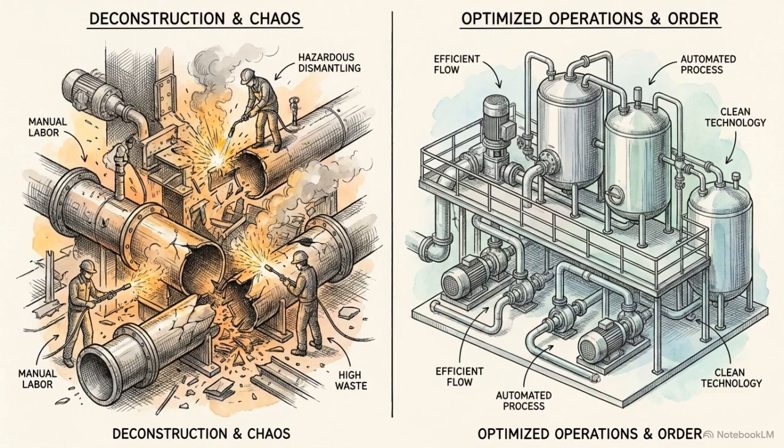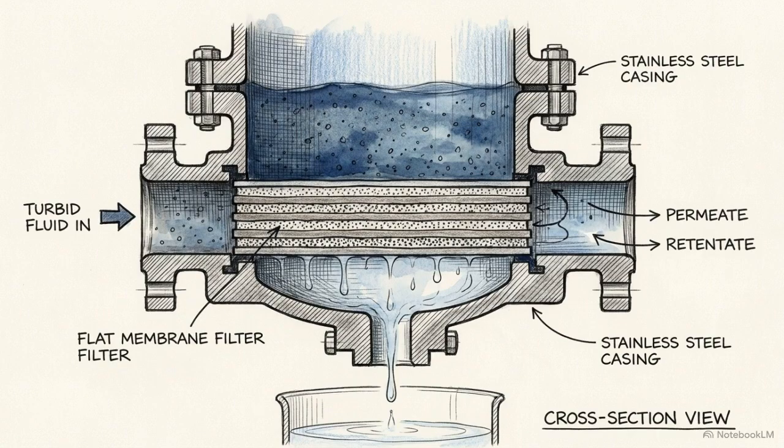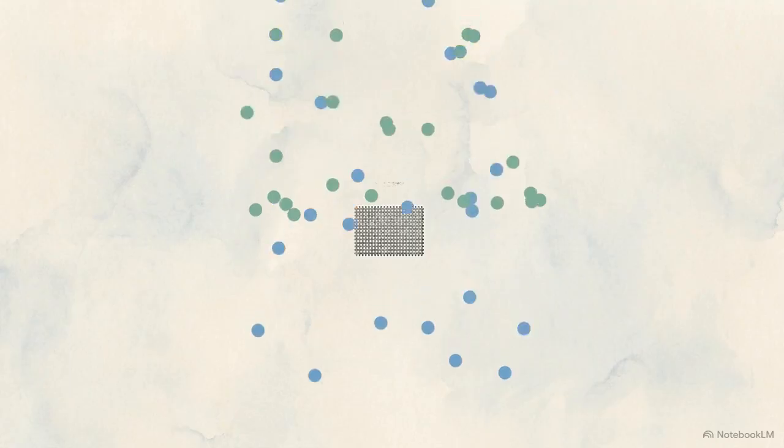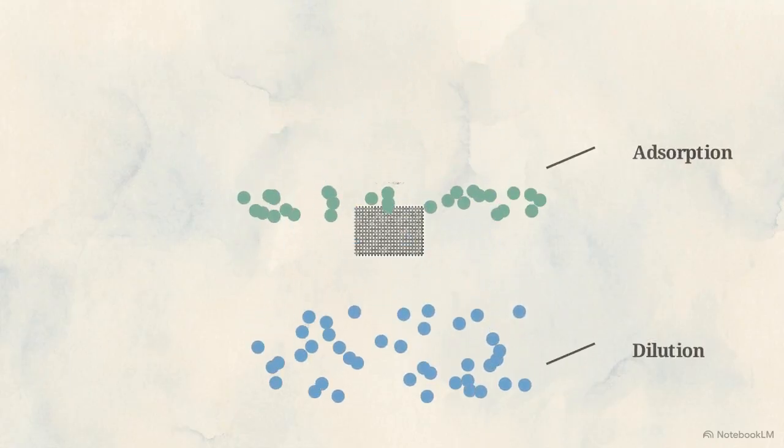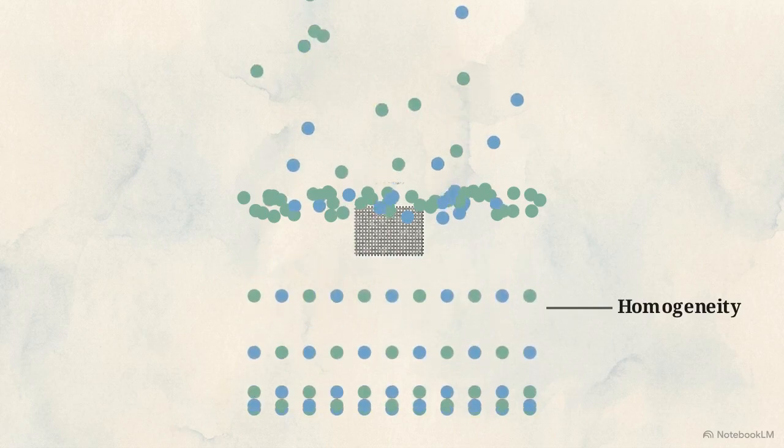The final manufacturing phase involves transferring the formulated drug product to an external partner for sterile filtration, aseptic filling, capping, and freeze drying. Sterile filtration presents a strict fluid dynamics challenge. The manufacturing team must ensure total homogeneity of the fluid passing through the membrane, preventing the sterile filter from diluting the excipients or absorbing the active protein.